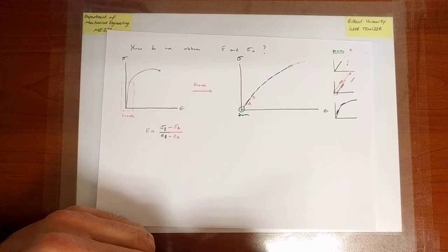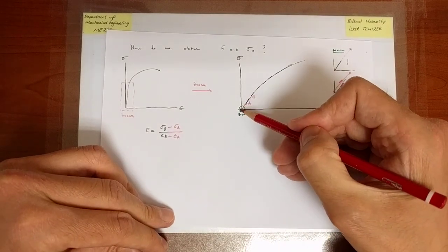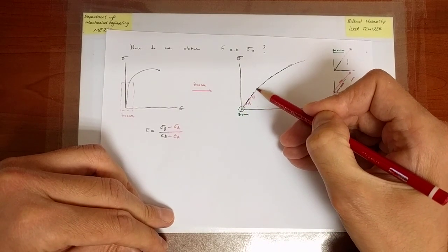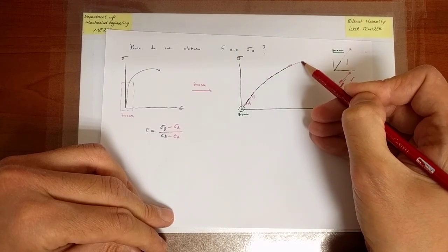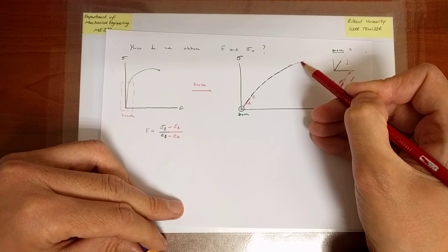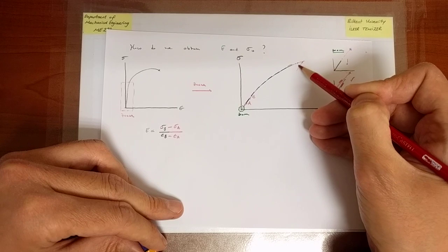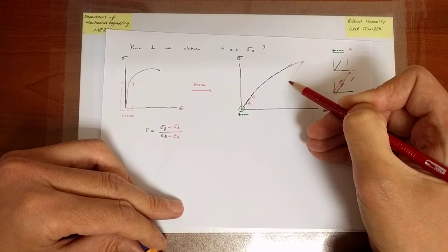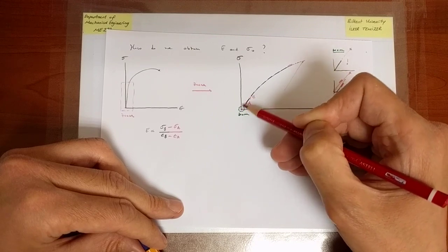And essentially what we are expecting here is that, well, I load the material, and what plasticity means for me is that when I unload, say from that point, I'm going to unload on a curve that is going to have a slope that is similar, again this is an idealization, to the slope in the original elastic portion of loading.